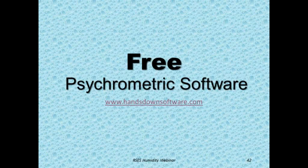Because as the temperature outside goes up and down, they recommend that you turn your humidity control system, your humidistat, either up or down to match the changing outside condition. And manufacturers actually make humidistats now that have an outdoor sensor so that it will automatically readjust when the outside temperature changes, so the customer doesn't have to fool with it. But I think technically is where that question was coming from.